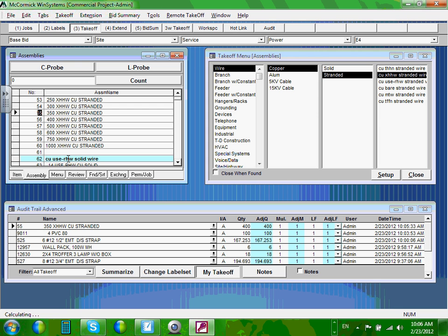Okay, so we have taken the service. Now, if you have 2 runs, like I think you guys have 2 runs, what do you do? You take the same value twice, or you multiply by 2. So the 400 multiplies by 2 because I'm running 2 runs, 800. And the 200 runs of conduit times 2 becomes 400. Make sense? Because you're parallel. Any question, guys? And the rest is history.